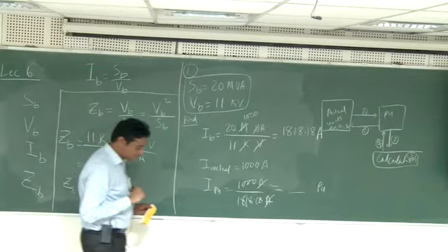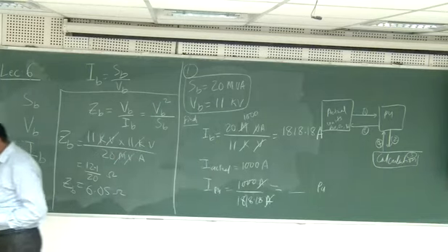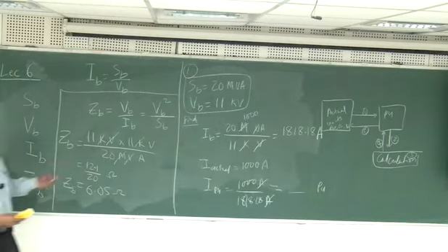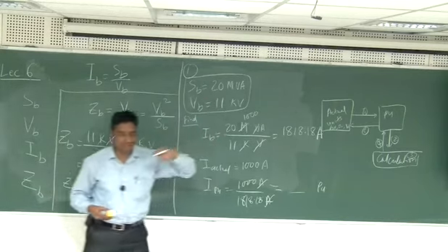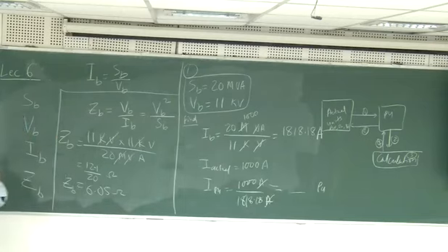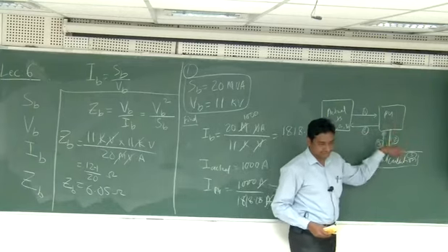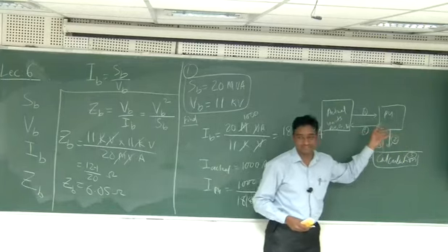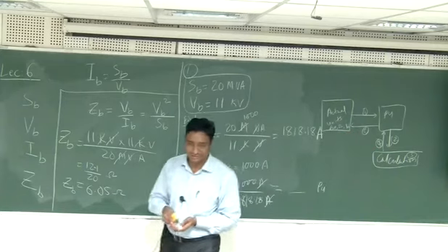So now what happens? Suppose in the exam there is a question given. One student chooses different values, like 20 and 11. Another student may choose 30 MVA and 11. Then they both solve the problem. The in between solution, like this part, is all different because the base is chosen differently. But when finally the results are converted, both answers will match if they are correct.